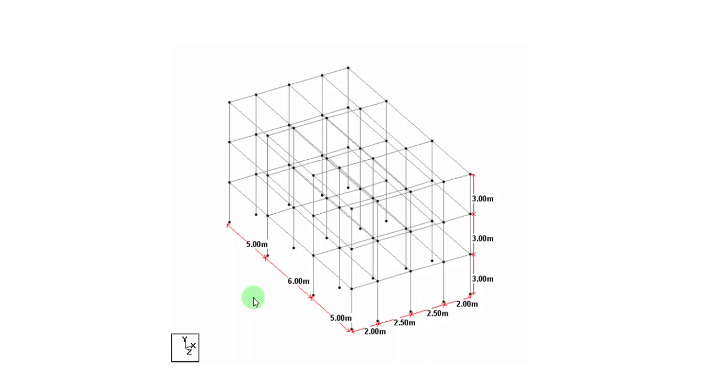Welcome everyone. In the last session, I had asked you to model a few of the problems. Here is one which I'll tell you how you can model very quickly in STAAD. To do this, we will model one of the planar models, and by using the translational repeat command, I can complete this very quickly. So let us do this. Let us focus on this planar model first.